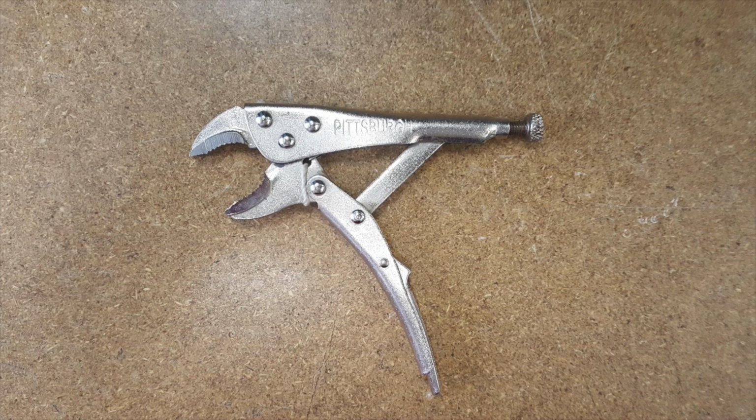This pair of locking pliers provides a practical example of a linkage. As you can see, the plier assembly forms a 4-bar with 4 revolute joints. Sometimes you may need to design a linkage to travel along some specified path, or to be in a certain position or orientation at a certain time. This can be accomplished using graphical position linkage synthesis.